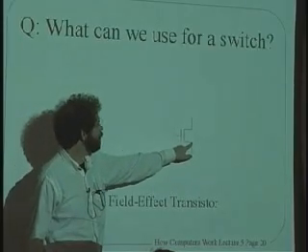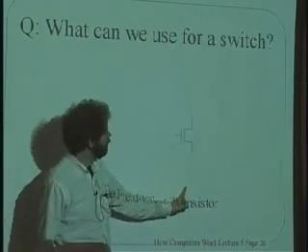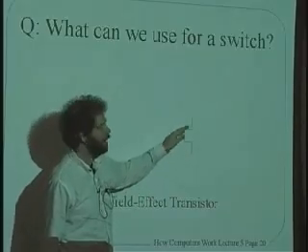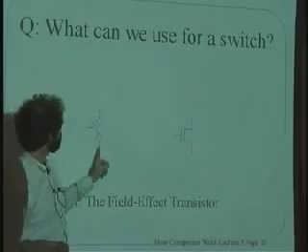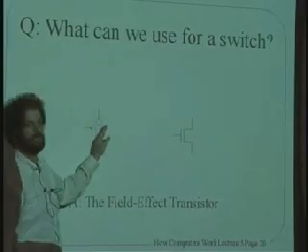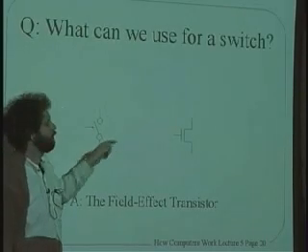And this thing, one is called the source and the other one is called the drain. The idea is that electric current is trying to get through this thing, and this is a gate that says whether or not it gets to go. In the same way that this is a switch, the electric current is trying to get through this path here, and whether or not the switch is closed depends on whether the gate is high or low. And that's how these things work.